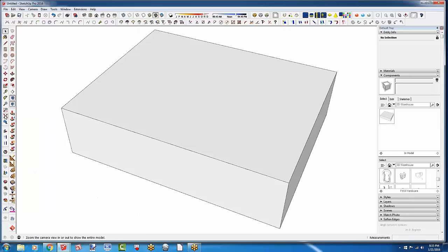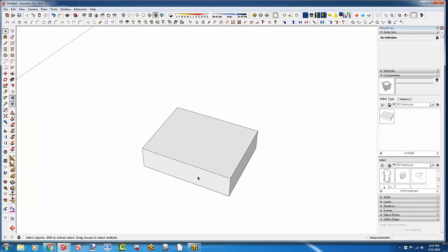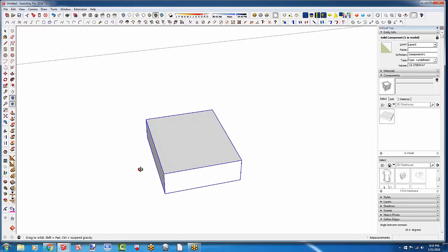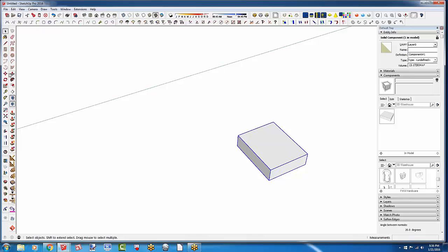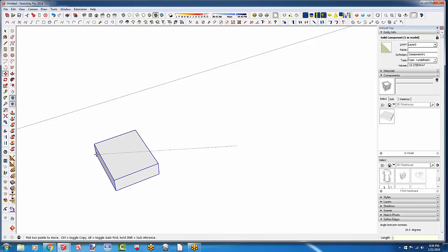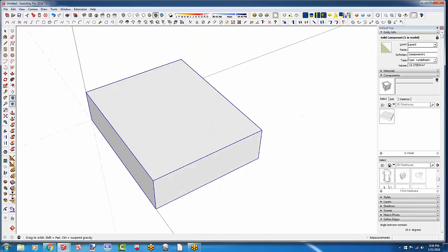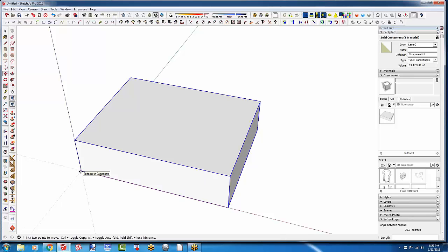And then when I hit zoom extents, I was able to zoom in on the chessboard itself and move it back to the origin, which you can do by typing 0, 0, 0 in square brackets. That moved the point that I'd started with by typing the coordinates in the square brackets. I got it back to the origin.